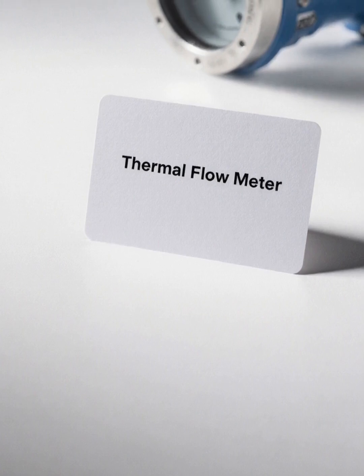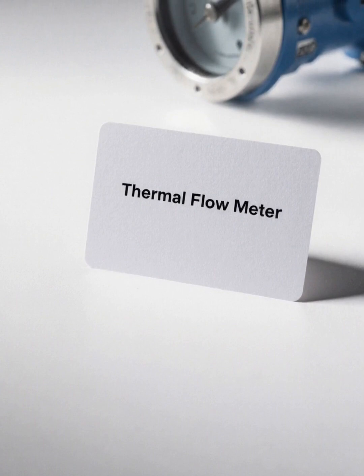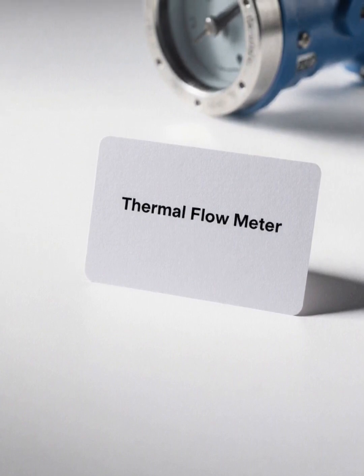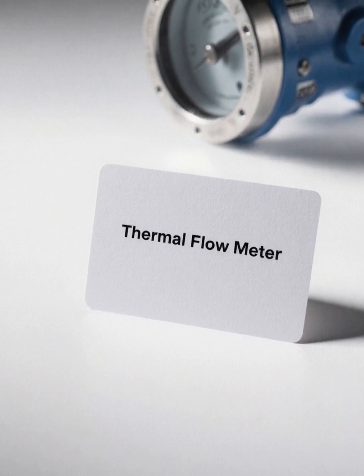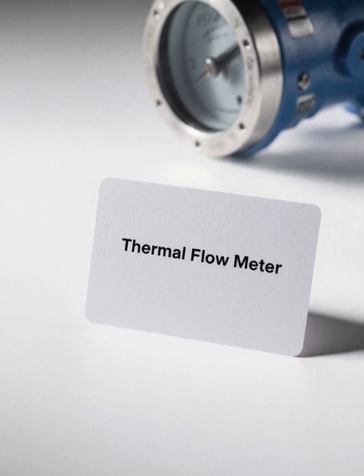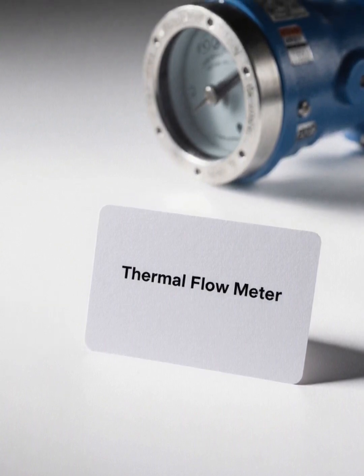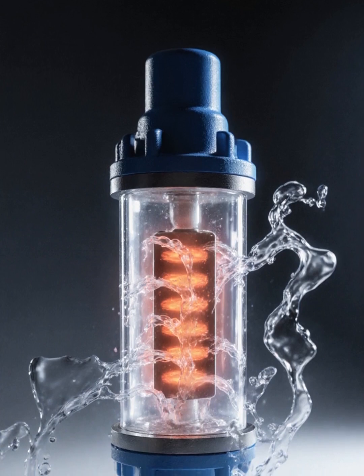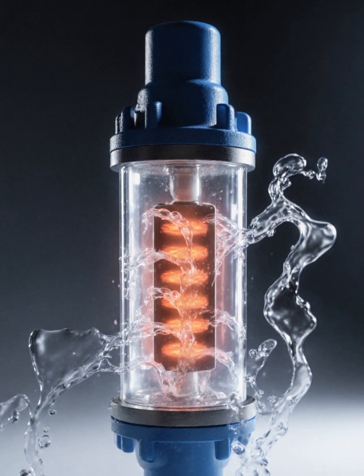2. Thermal mass flow meters. Heat is added to the stream, and the energy needed to maintain a constant temperature, or the resulting temperature change, indicates mass flow. Thermal mass flow meters operate based on the thermal dispersion principle.